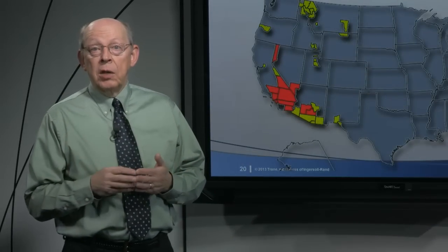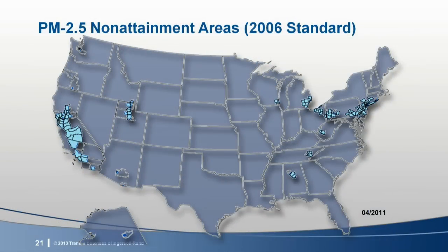The ventilation rate procedure also requires filters in PM 2.5 non-attainment areas, those areas where the concentration of particulate matter 2.5 microns and smaller exceeds the national standard. Here's the latest EPA map for PM 2.5 non-attainment areas. At least MERV 11 filters are required for systems in the shaded locations. Air handler fans must be selected to provide the required airflow whether the filter is clean or dirty.